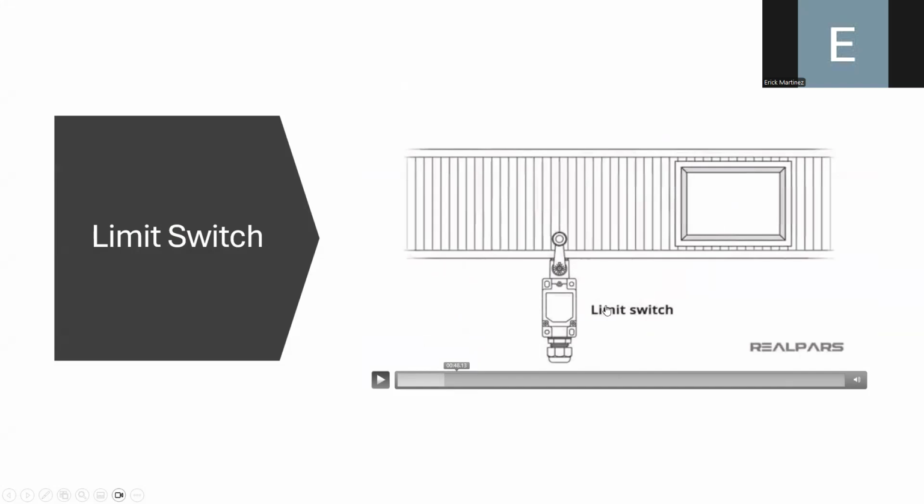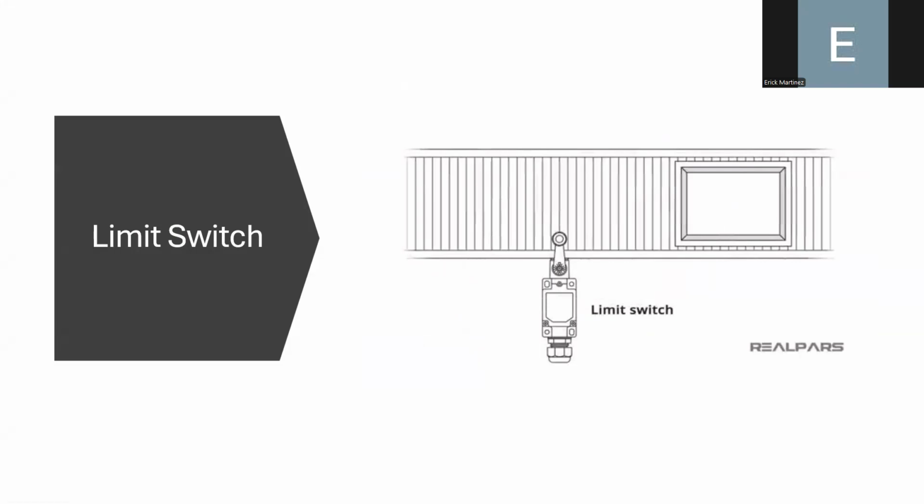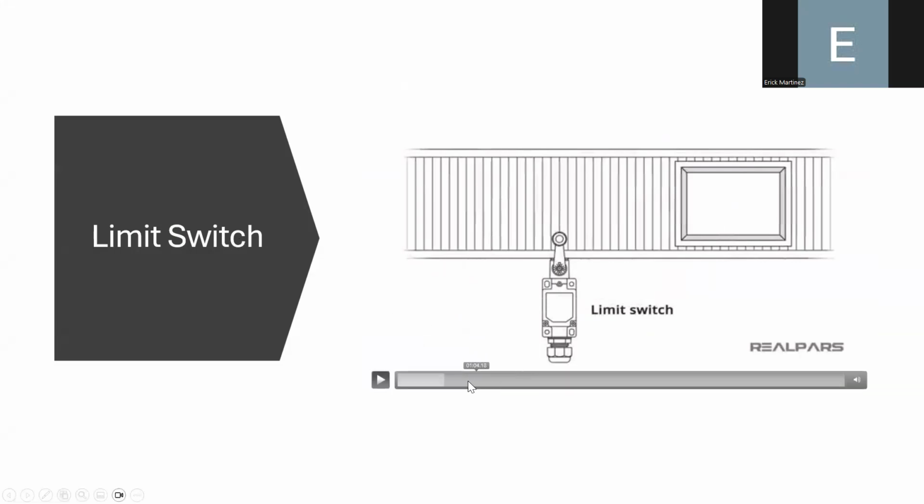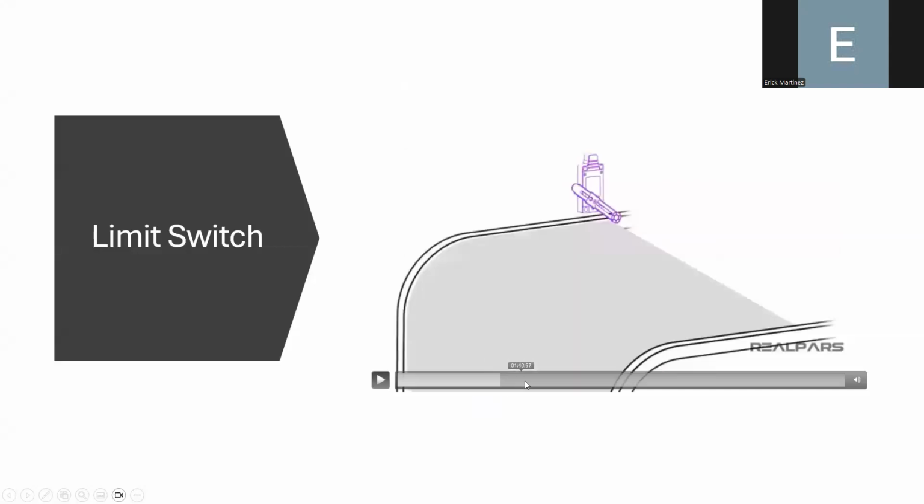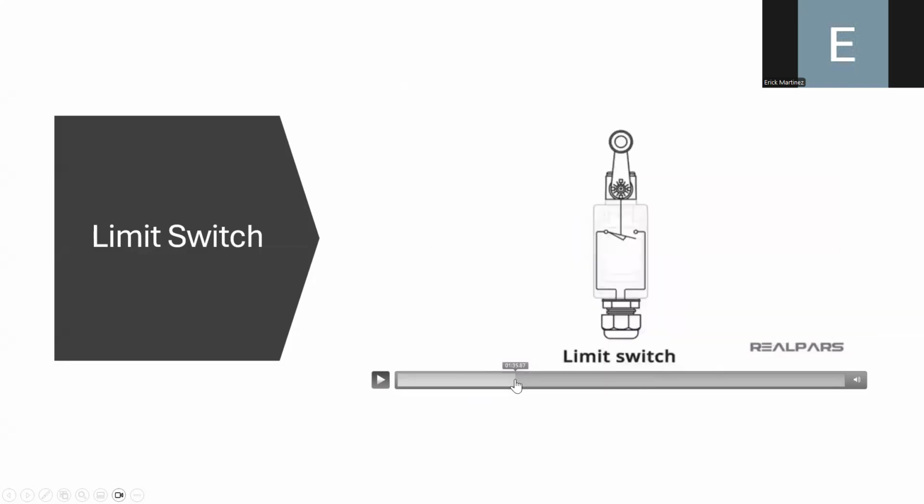You have here a limit switch with a roller, and when this box is moving, the roller will also move. But the movement of this roller will produce that a contact can be closed or open. And in this way, we can detect the presence of a moving object. Okay? So, well, this is another example. We have here another type of roller. This is basically detecting how this gray part is moving around this transportation band.